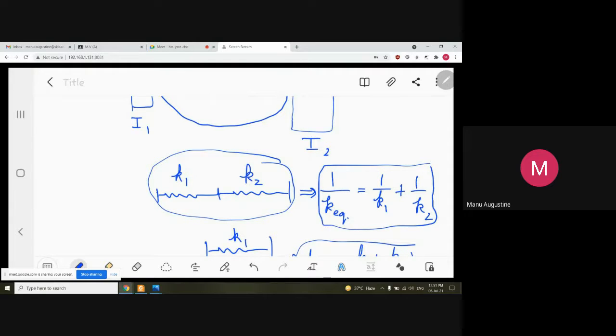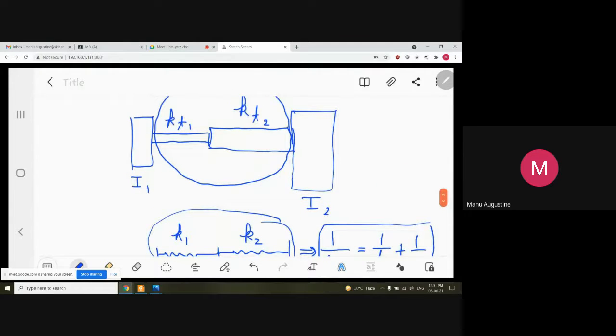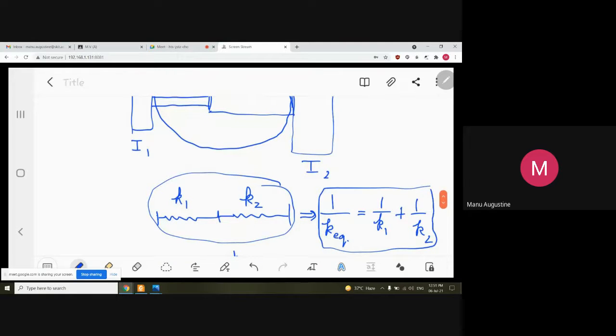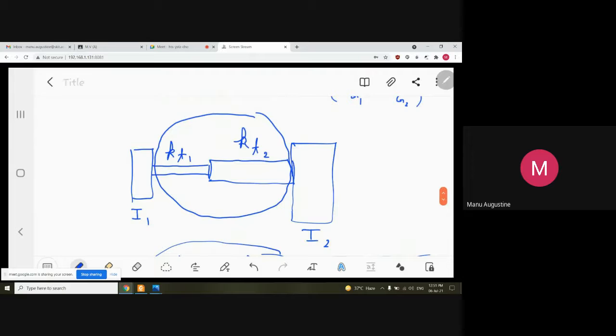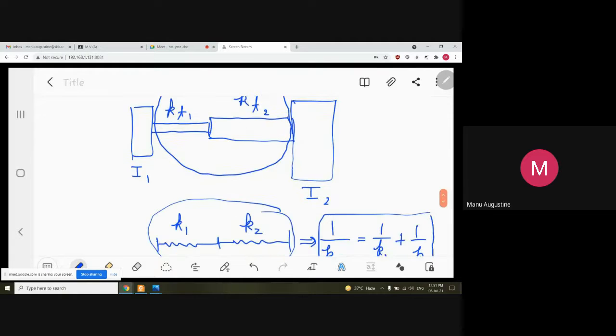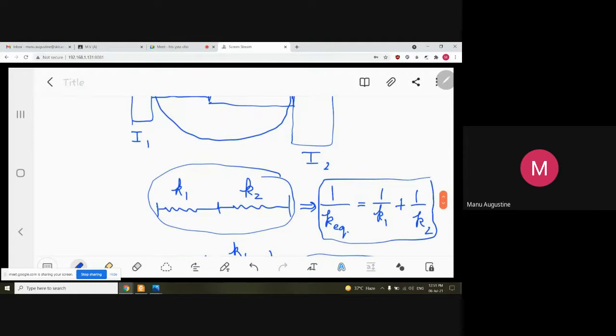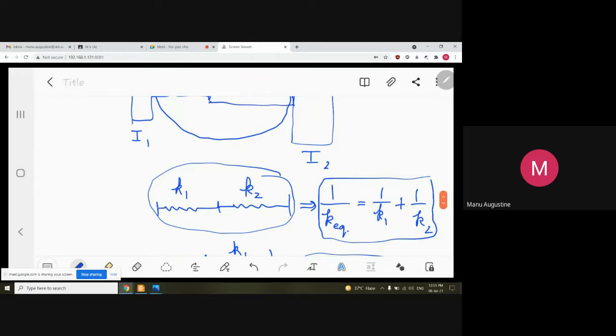So all that we need to do for this one is, now since for straight springs you know the equation like this, it's exactly applicable in the same manner for torsional stiffness too. So KT1 and KT2 are torsional stiffnesses. They are obtained in rotation, but don't worry, the formulae for conversion into an equivalent shaft would be exactly similar to this.